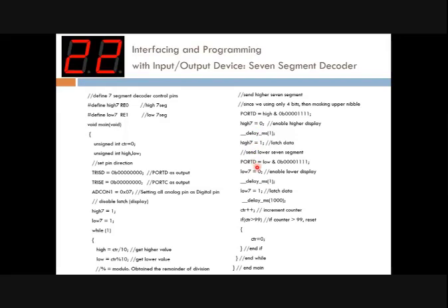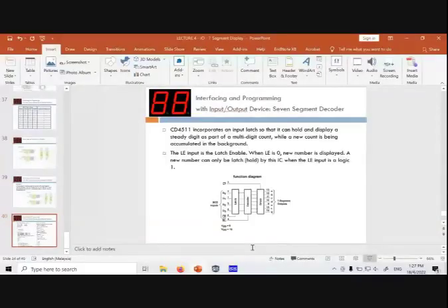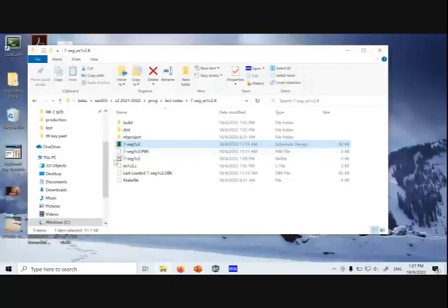After that we do the bitwise operation, but this time we turn on the other 7 segment, and then wait for 1 second. This one is 1 milli, this one 1000, which we can observe later on. And then we increment the counter, and if the value is higher than 99, reset it back to 0. So we look at an example first before we stop our class.